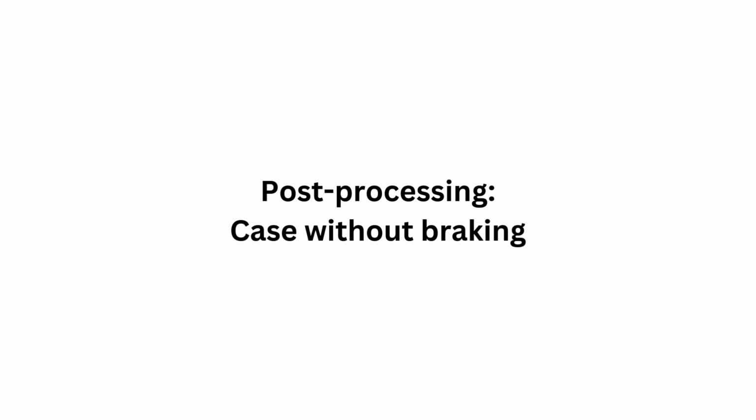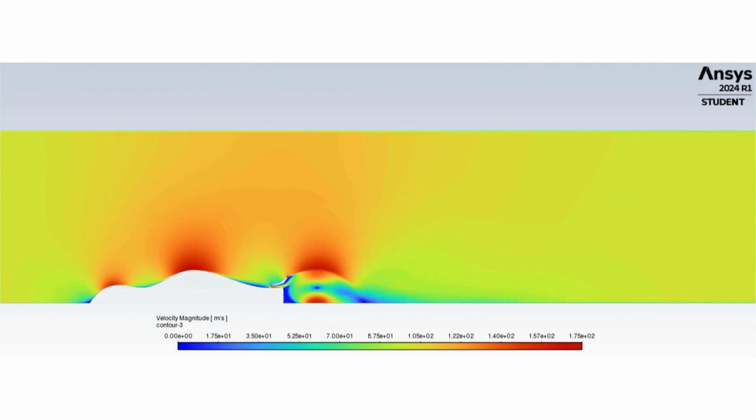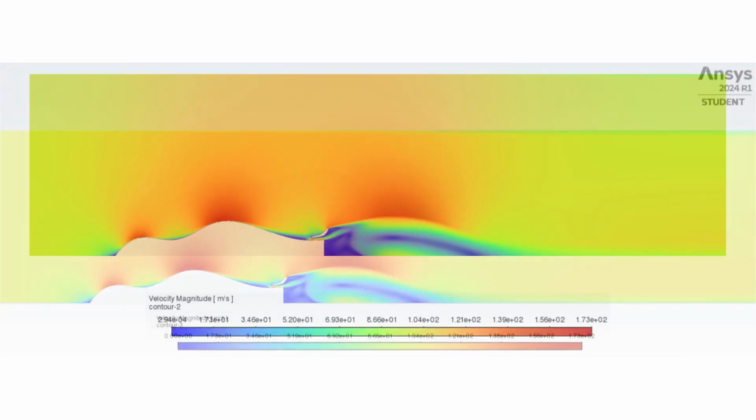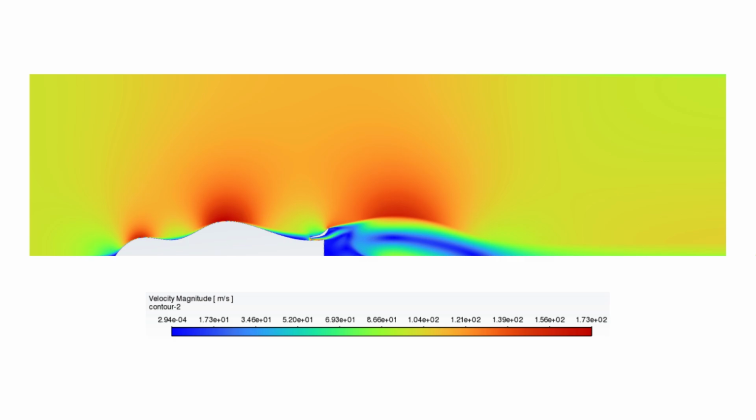By analyzing the presented CFD results, we will examine the velocity, pressure, and turbulent kinetic energy to understand the aerodynamic forces, lift, drag, and downforce, caused by the car's wing. Starting with the velocity analysis, we observe that the velocity magnitude plot shows a high velocity region above the wing and a lower velocity region below it. The sharp gradient at the trailing edge of the wing indicates significant airflow deflection.